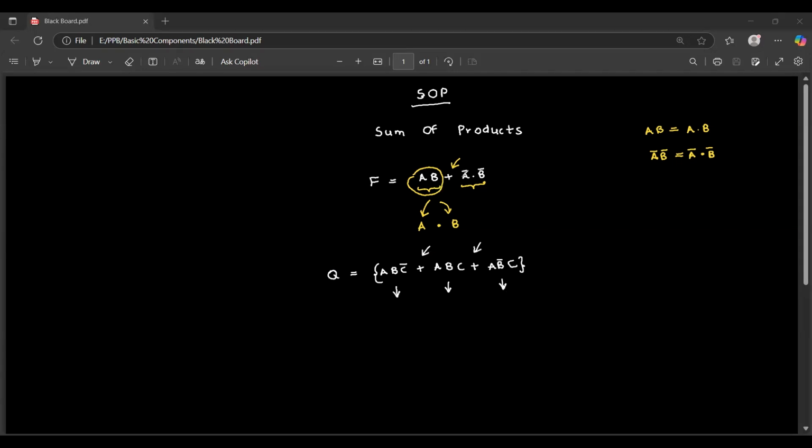We can use multiple OR gates and multiple AND gates, but the expression is still a sum of products. For example, with four inputs, let's say we have z equals a b c plus a bar b bar c d plus b c d bar.